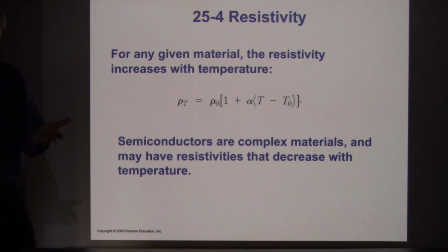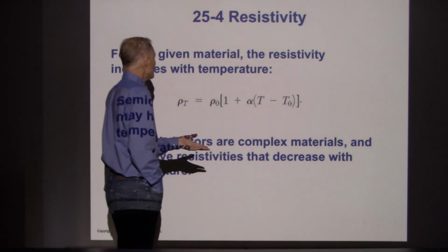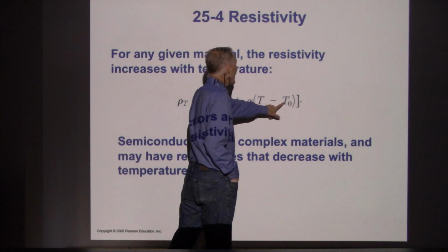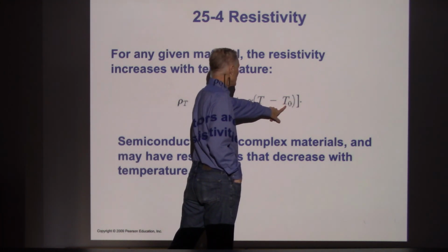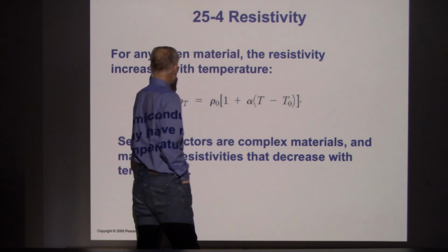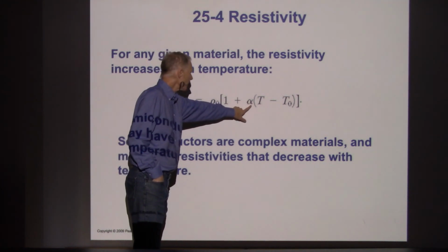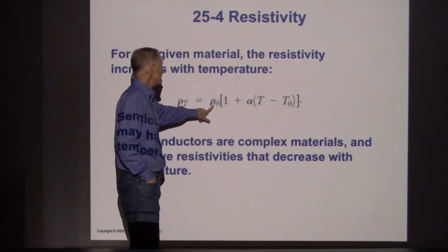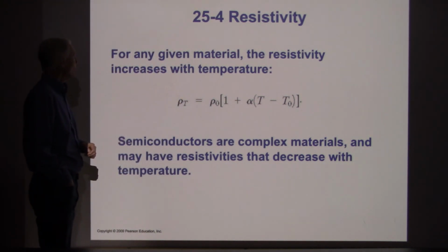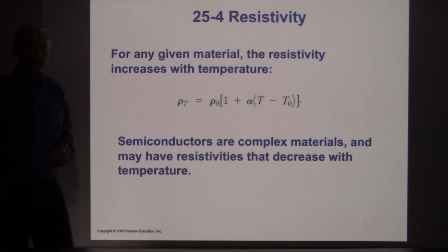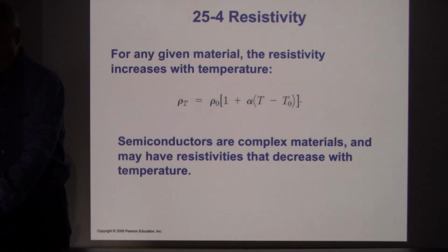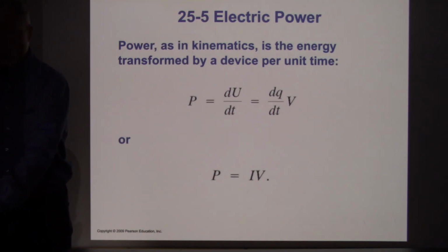Okay, here is the resistivity as a function of temperature. As the temperature rises above our reference temperature of 20 Celsius, the resistivity goes up. I can plug in an alpha, I can plug in the standard resistivity value, and I can calculate how much the resistance is going to be. So that's just a formula we can plug into.